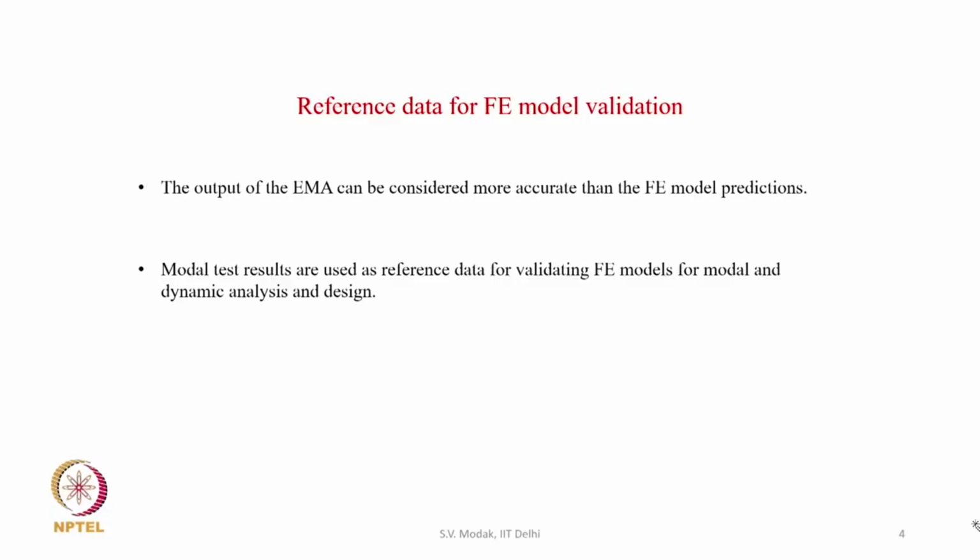However, the FE model predictions may be associated with some inaccuracies, as we discussed on the previous slide, and therefore, they are not supposed to be as accurate as the test results. They may be precise. So, we may calculate the dynamic characteristics to a good precision, right, but they may not necessarily be as accurate. That is why, if we want to compare the accuracy of FE model predictions, they can be compared against the modal test data, and that is why the modal test data is used as reference data for determining the accuracy of the FE model predictions.